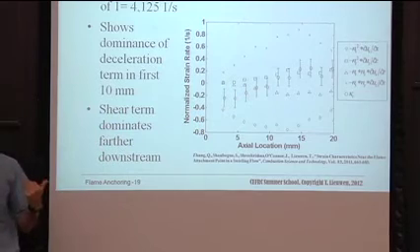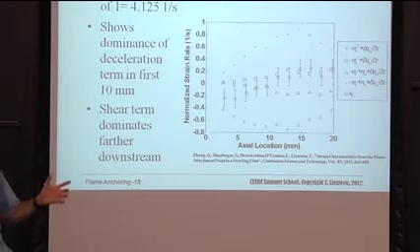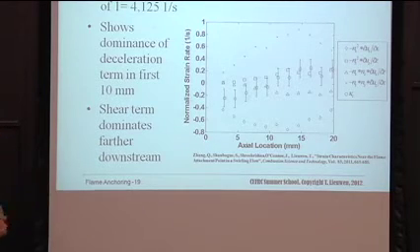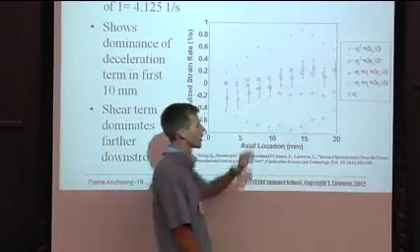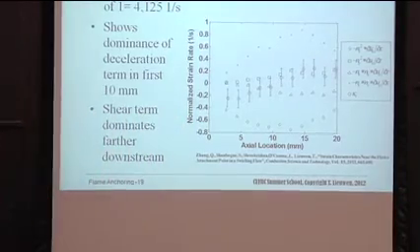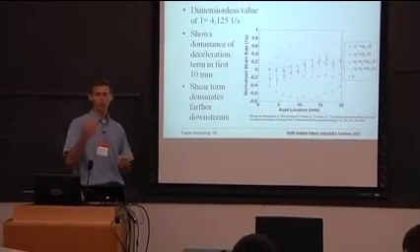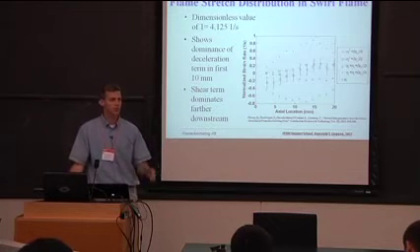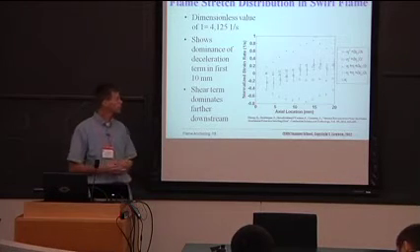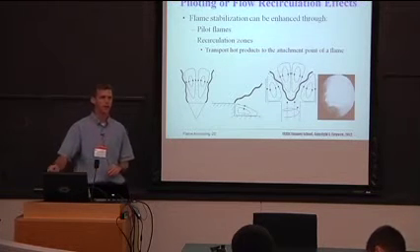So what this tells you is that in this swirl flame where we took this measurement, although the flame is sitting in this strongly positively stretching shear layer, the flame is actually being negatively stretched right at the attachment point. Farther downstream, it reverts to a positive stretch. This is a really interesting problem. Just because of its pure sensitivity, you're taking two terms of opposite sign, and one of them you're multiplying a big number by a small number, all kinds of crazy stuff can happen. Lots of sensitivity to stuff. Scaling flame stretch rates in shear layers is a really interesting problem. Okay, does anyone have any questions about that?